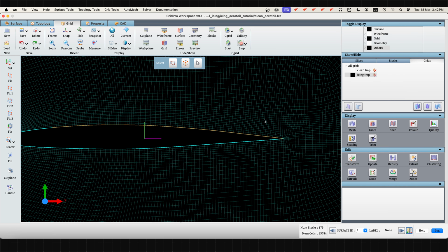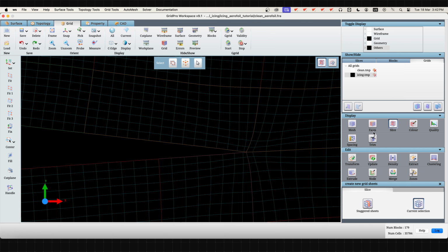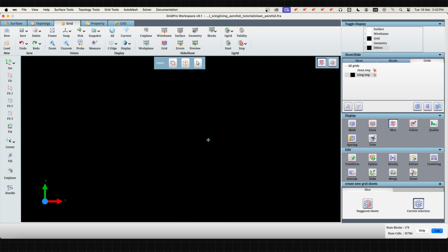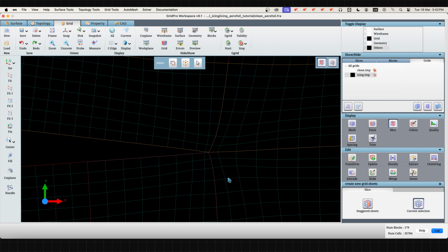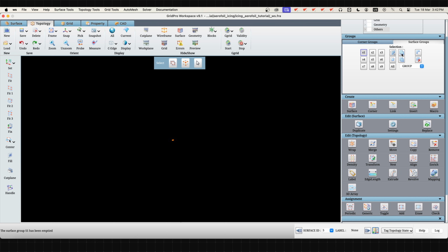We can create an internal surface to capture the sharp trailing edge of an airfoil more precisely. Open the surfaces in the newly launched UI within the same working directory. We need to create surfaces extending from the airfoil's trailing edge to the domain. For that, we will take the corners of the intersection of two surfaces forming the airfoil. Put the airfoil surfaces in the Surfaces group.